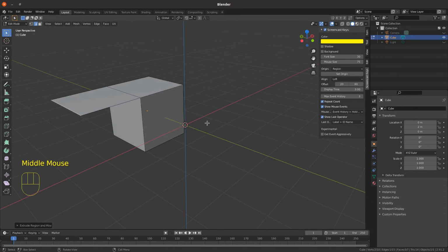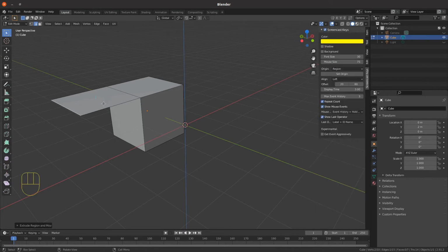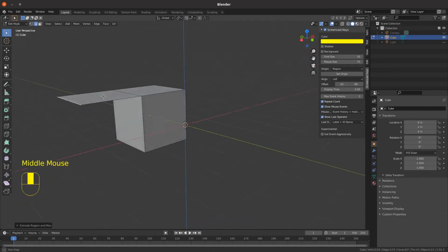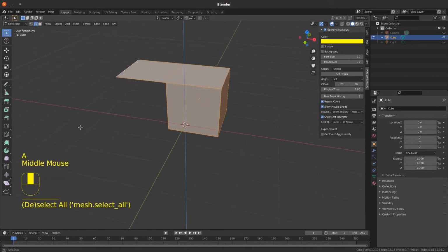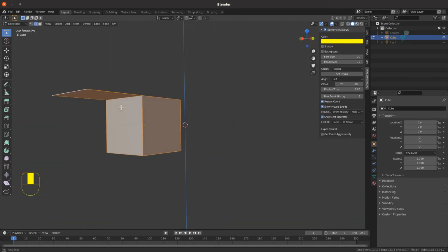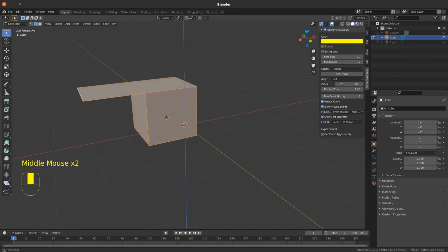And Blender has a thing called a face normal, and if I go into overlays and just show the face normal, you'll see that this face is partially selected, so it's showing the normal direction, and the face normal points up, it doesn't point down. If we select all, it hasn't done that. So the normals are pointing inwards on the box.